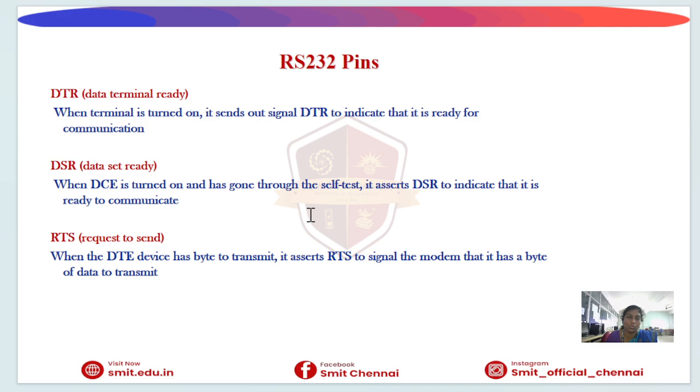Now the RS-232 pins. The RS-232 has important control signals: DTR, DSR, and RTS. What is DTR? Data Terminal Ready is sent by the DTE to indicate it is ready for communication. Next is DSR, Data Set Ready. It is sent by the DCE to indicate it is ready.